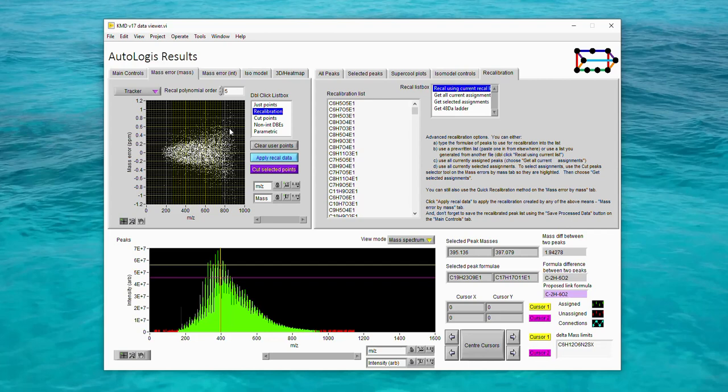However, on normal data such as we have here, this Walker mode would be overfitting the data and so would not normally be used. However, as we have this file open, we'll use it for demonstrating how to set Walker mode up. So to select Walker mode, again you go back to the recalibration dropdown and choose the Walker option there.